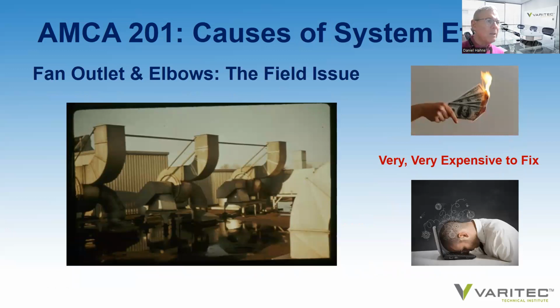Well, do breaking the back of the fan duct arrangements actually occur? And the answer is yes, absolutely they occur. And if it's installed like this, it is not going to be a good day, because it's very expensive to correct, especially for larger fans, because those housings are welded to their frames, and you would have to grind off all the welds to turn the frame, and now you're reducing the effectiveness of the coating of the fan, etc.